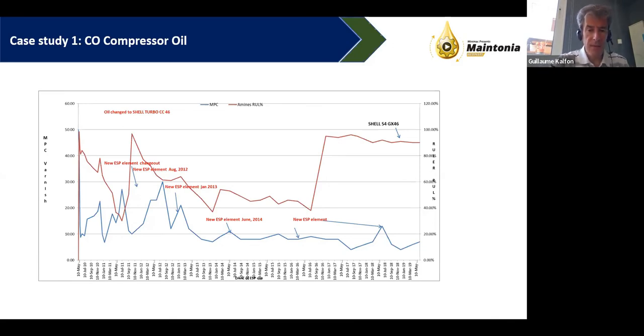And this is on the right hand scale, please. Okay, so it needs to be close to 100%. And you see what happens to this oil if you follow the red line. When we had a lot of varnish contaminants, then the slope of the red line was steep, meaning that the antioxidants were lost fast. Okay, that's not good. It means short life. And then in the middle period, we see that the slope became flatter.